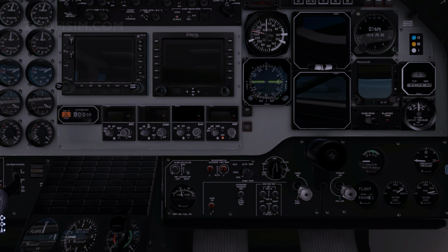When the air cycle system is producing maximum cooling, the refrigerant compressor is engaged, and the cooling cycle of the vapor cycle system is initiated. Cabin temperature can be automatically controlled by presetting the cabin temperature selector to the desired temperature and setting the mode control switch to automatic. The temperature control of environmental air can be controlled manually by setting the mode control switch to manual and holding the manual temperature switch to the increase or decrease positions.